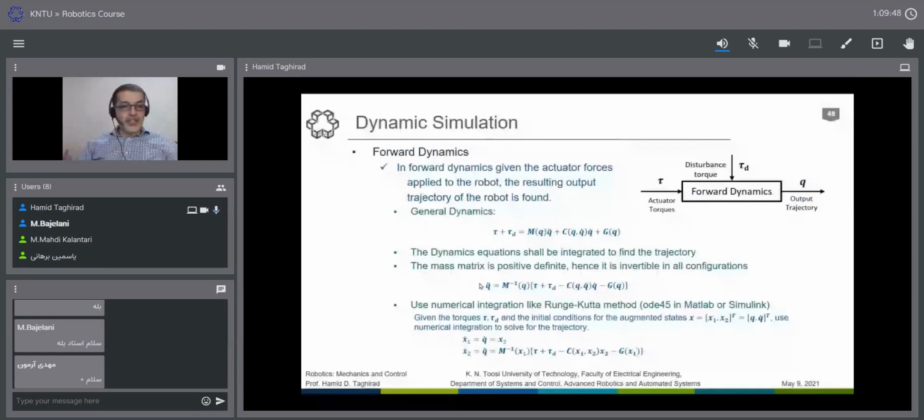I will change that, and also add the dynamic formulation for this. This is the benefit of it, and how we can use it. Now, consider that we have the Christoffel matrix, or, as you see here, the V matrix, we have the linear regression, we have the passivity, we have the skew symmetricity.